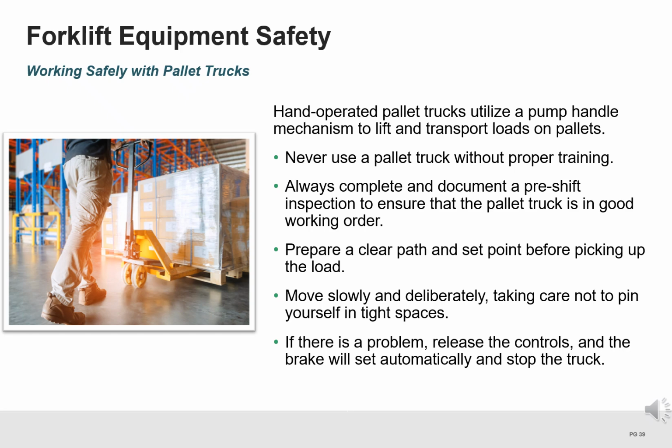Plan your path of travel and your set point before moving the load. Operate slowly and with control, especially in tight spaces to avoid pinning injuries. If a problem occurs, release the controls. The brake will engage automatically and bring the truck to a stop.